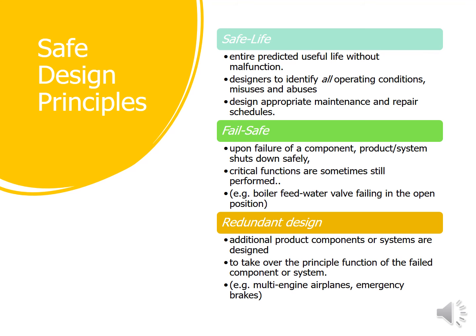Safety design principle. Save life. First, ensure predictable useful life without malfunction. Designers identify all operation conditions, misuse or abuse, and design appropriate maintenance and repair schedule. Number 2, fail safe. Upon failure of a component, product and system shut down safely. Critical functions may sometimes still perform.